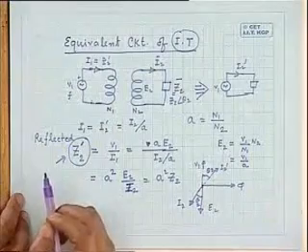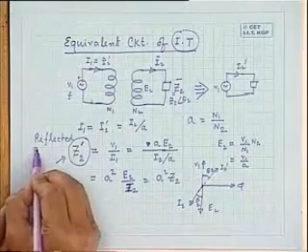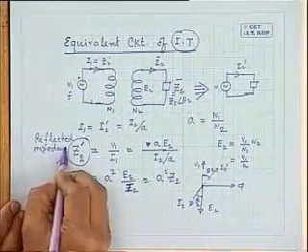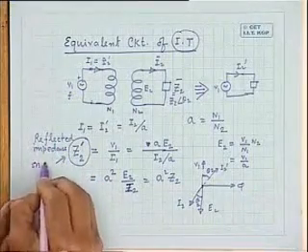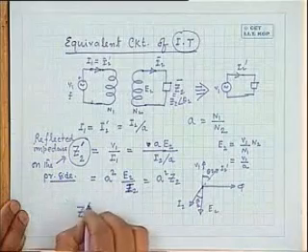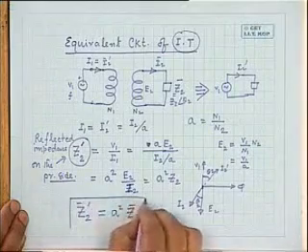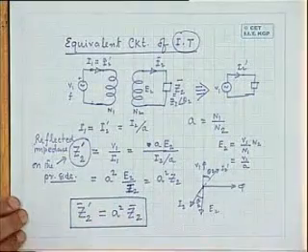The same way as we have said, I2 dashed is the reflected current on the transformer primary side. So reflected impedance on the primary side, Z2 dashed, is A square times Z2. This is important. In fact, any impedance on the secondary side becomes A square times as seen by the supply, where A is the turns ratio of the transformer, N1 by N2. Is that clear?